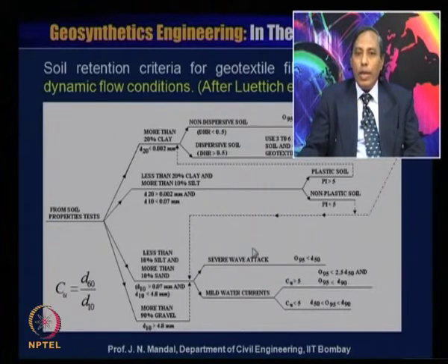It also depends upon the soil condition, whether it has less than 10% silt and more than 10% sand, and also D10 should be greater than 0.07 millimeter and less than 4.8 millimeter, and for more than 90% gravel, D10 greater than 4.8.